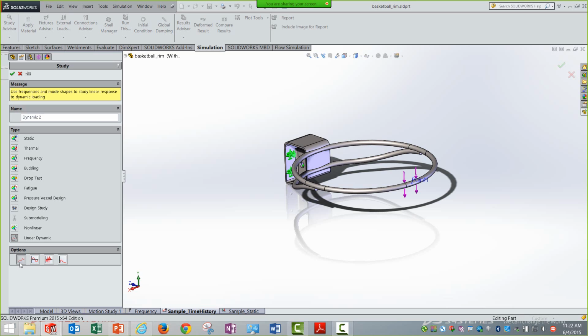One of them is using the mode shapes or the modal details, wherein we do the modal analysis first, understand the frequencies, mode shapes, mass participation factor, and those results are further taken. Of course, this is all happening inside the software for calculating the detailed stresses and deflections under dynamic loading. As well, it can be an iterative process or a simple direct sparse process, and what we call nonlinear dynamic, we can use that method as well.